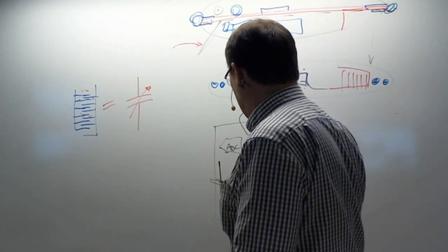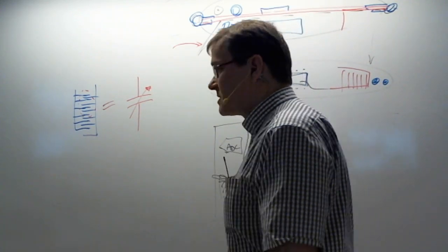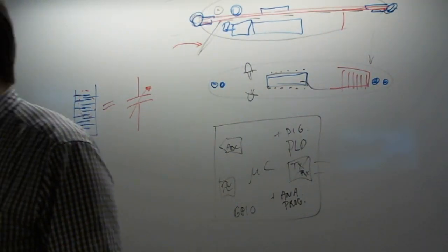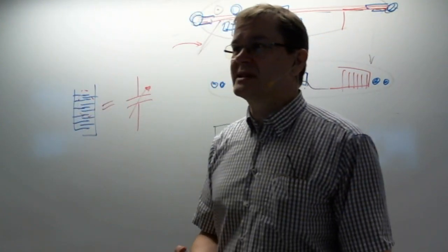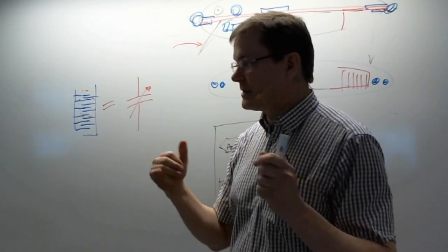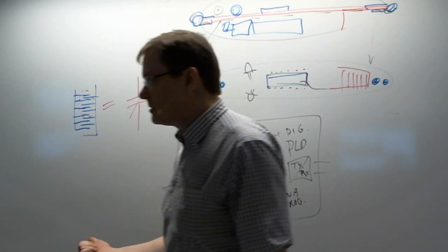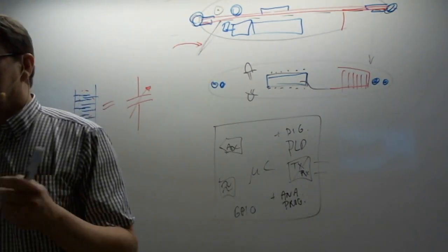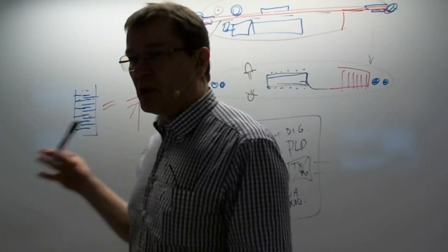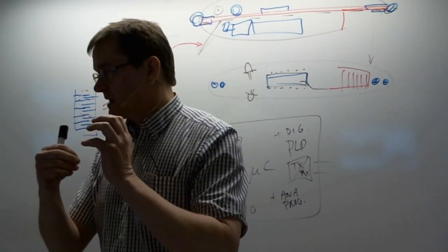And of course, really flexible GPIO. Practically, for the digital I/O, there are no real restrictions on which pins you can use. So for digital I/O, you can use any pins. For analog I/O, you can use only a couple of ports, but that's already a lot of flexibility.